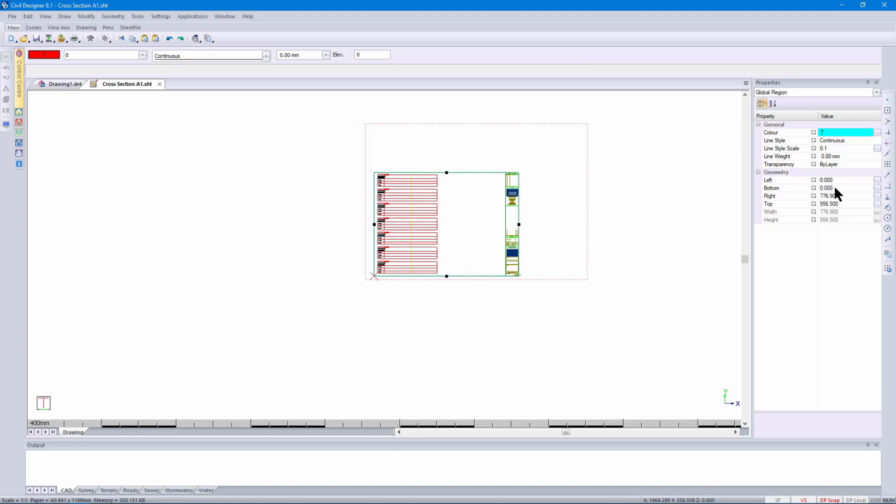The alternative, which doesn't always work very nicely, is to go and say plot generate and choose the A0 sheet file. You can then choose any size lower than that. However, that does cause problems by making the text smaller. Here, with this method, you have far better control with the text heights and the scale annotations.